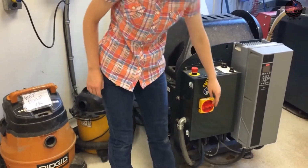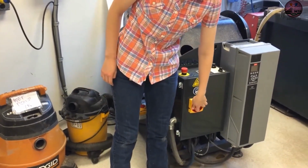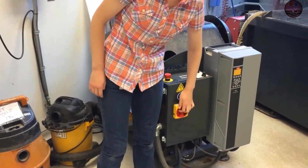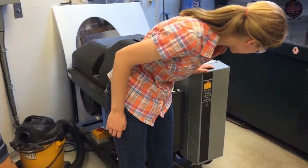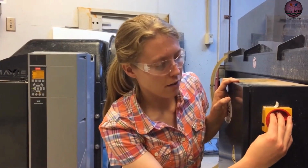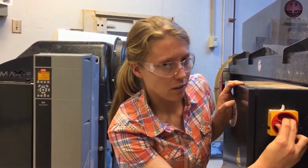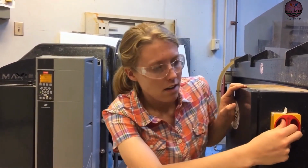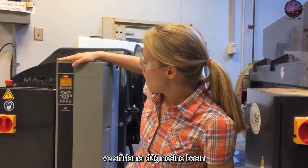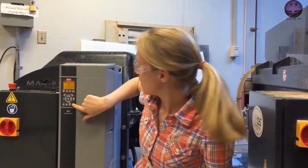Next, turn this red switch clockwise to the 12 o'clock position. When the pump first turns on, give it a few seconds to start up. Next, turn this red switch on the front of the water jet clockwise to the 12 o'clock position. And finally, go to the pump here and press the reset button.